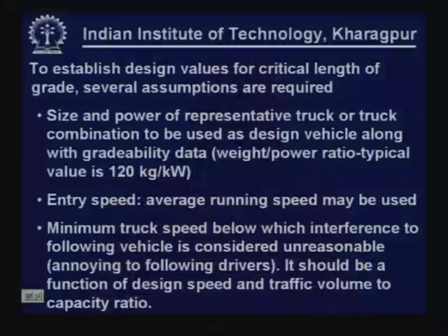Now, to establish design values for critical length of grade, several assumptions are required. Number 1, the size and power of the representative truck or truck combination to be used as design vehicle, along with gradability data, that is weight power ratio.